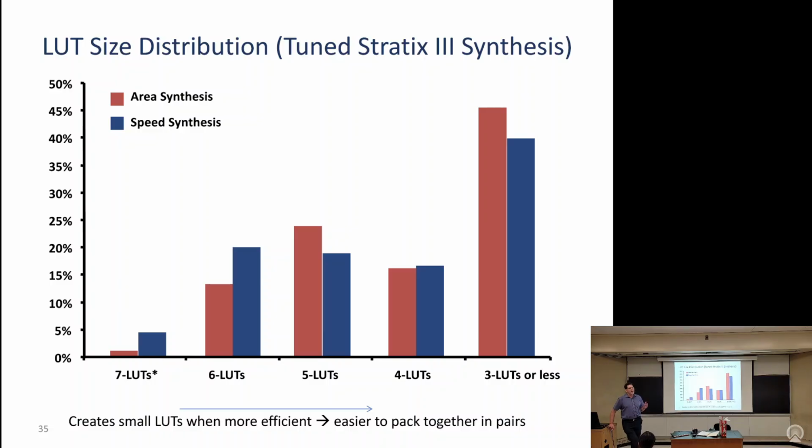What happens is it makes your routability bad. Basically you have to route these two signals on these two wires, okay? And then usually these muxes are actually wide data paths. So now repeat that for 128 bits. And now the select signal, you basically route that to bypass these SRAM cells. And you program these routing muxes in some special mode where they're not paying attention to their SRAM cell, they're paying attention to this other signal. And now we'll do the switching function.